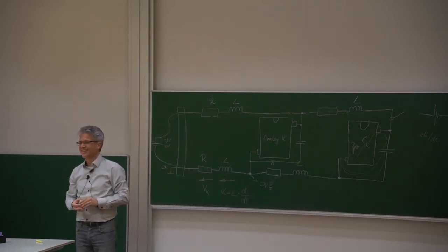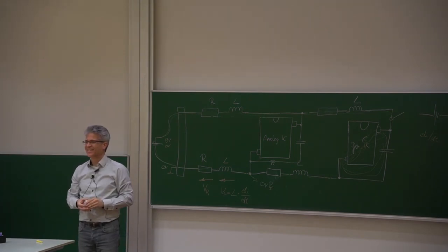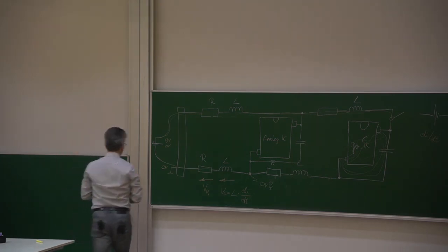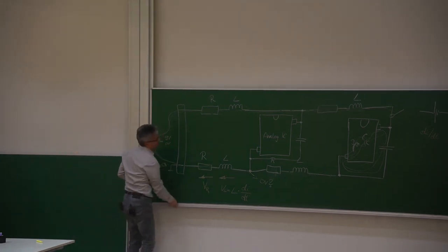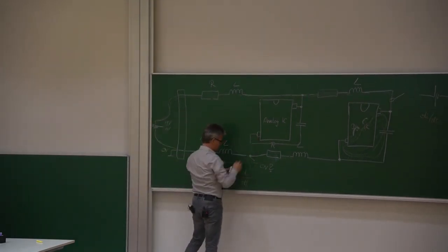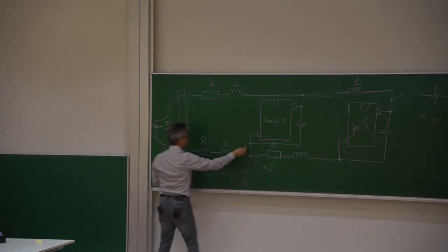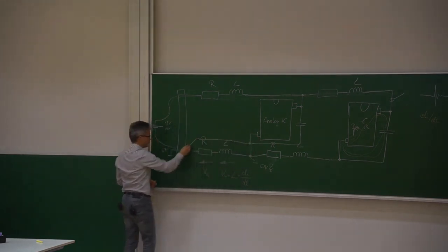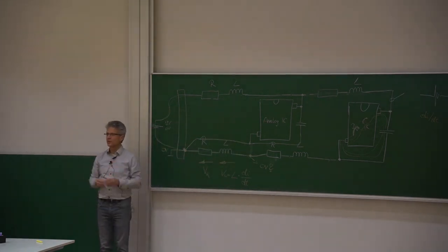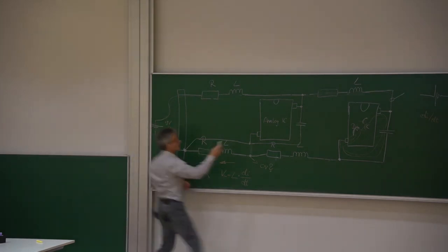Okay. I don't know if you can do it on the PCB, but usually you have those star connections to one ground so that you don't have a long path where they are coming in. Okay, so what about cutting this ground connection here and connecting the grounds over there to a kind of star connection, and also here for the VDD.